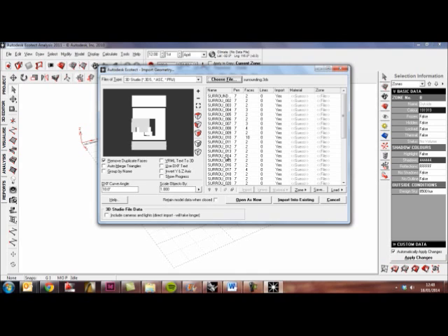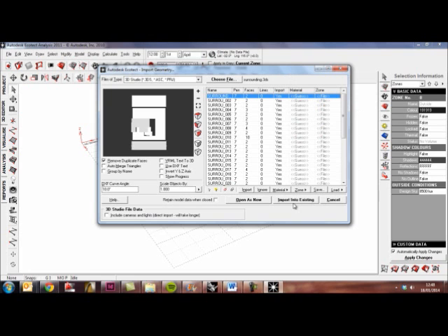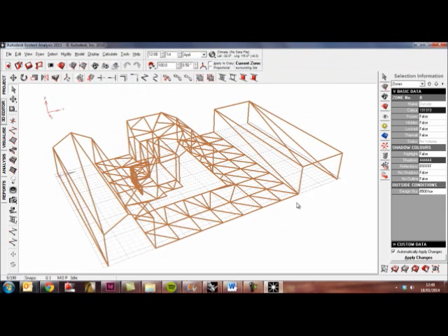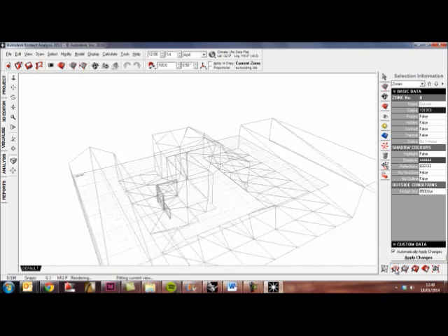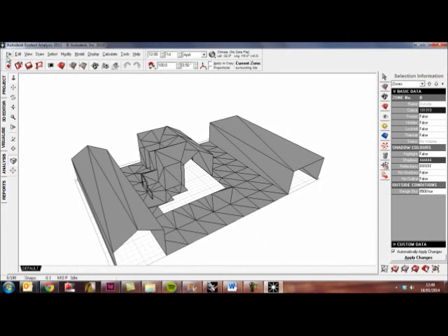Because it's all one layer, it doesn't matter a lot of these, but as I say, if you're coming from BIM, I could right click and set the zone by the item name if the export allowed you to do that. In Rhino we haven't really done that, so that's just for BIM people. But let's just import into existing. In it comes, and again if I go to Visualize and press this button here, which is Fit Grid to Objects, I will see it come in. Quite triangulated, but never mind that at the moment.